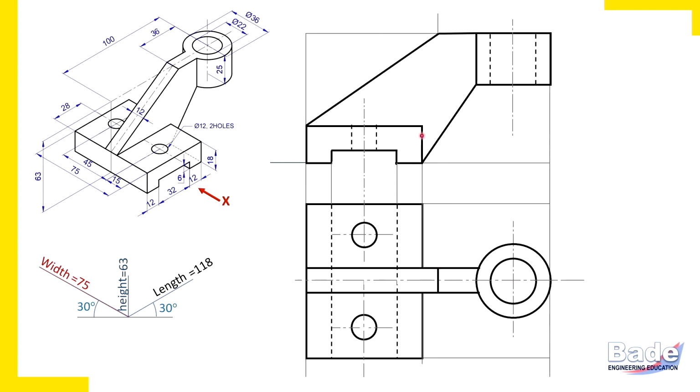Watch here. This edge, we have erased it or trimmed it. Of course, two visible edges don't intersect. So watch here, this edge, it is up to the plate. So here it is. A similar edge is on the back side, watch here, and it is up to the plate again. But one important thing is, from the top corner of the plate, there is an edge running parallel to the length axis, width axis. Similarly, from this corner also, there is an edge. So that edge will appear here as a hidden edge. So this dotted line is from this corner, the edge from the corner.